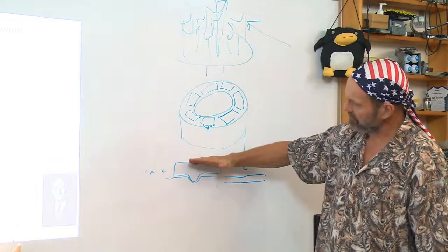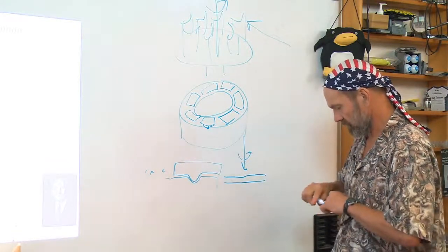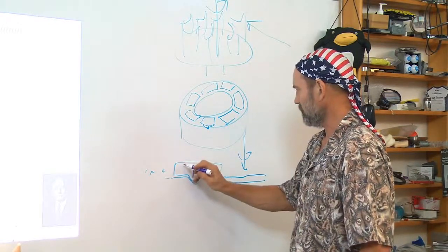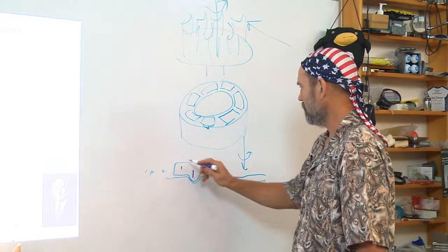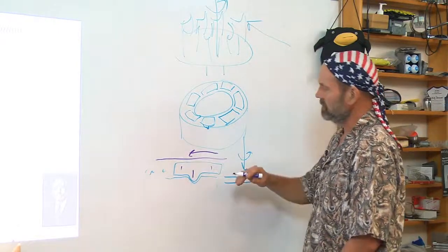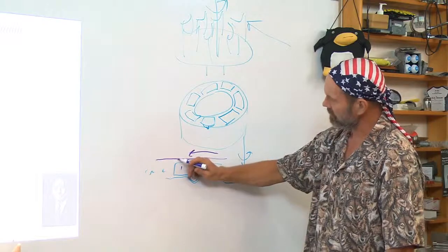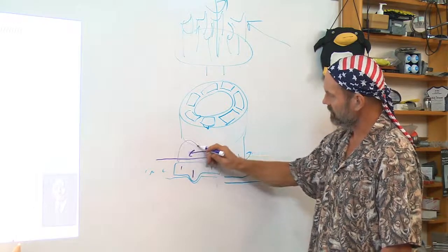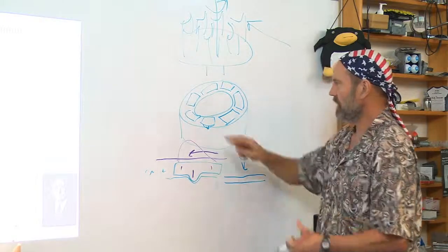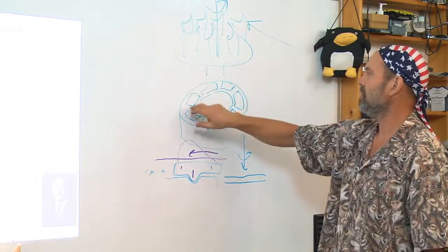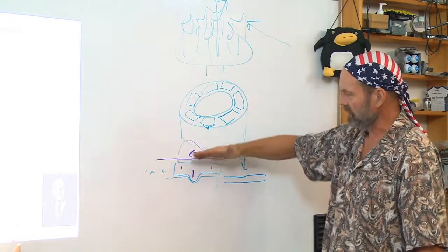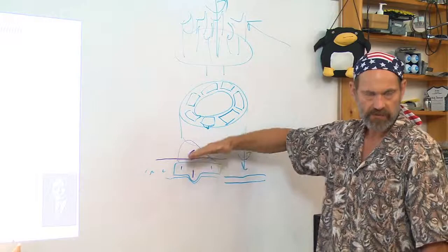If this tilts a little bit as the upper surface is moving, because you have a little bit of an eccentricity here, I'll build up this hydrodynamic wedge and pressure profile over this tilting pad. And when I have a whole bunch of these tilting pads, it's now very easy to get them all. You never have to worry about them being aligned in tilt because they will self-adjust.